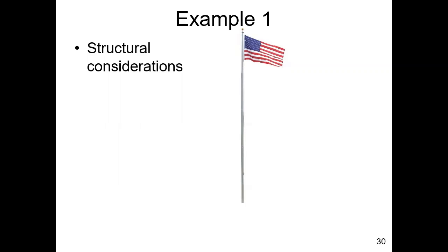You've heard of 100-year flood, 50-year flood, 10-year flood. There's 100-year wind speed, 50-year wind speed, 10-year wind speed. There's 100-year wave height, 50-year wave height. Anything that's probabilistic, anything that's random in nature as far as our loading functions, we can put into a probability distribution and come up with these extremes. And obviously, as you move across the country, if you go from here down to Florida, those ambient design conditions change. So once you know where you are, you've got some design conditions, some design wind speed.